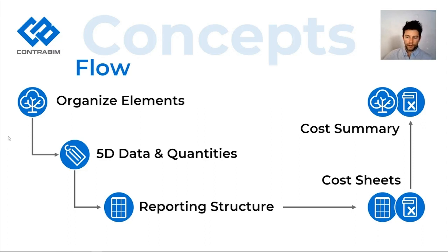From there, we can then start associating model data through our properties with those elements as well. We can add quantity properties there as well and do some mapping of different design tools parameters into these common quantity parameters. Our interactive schedules come in when we need to start pulling and organizing model elements into reports.